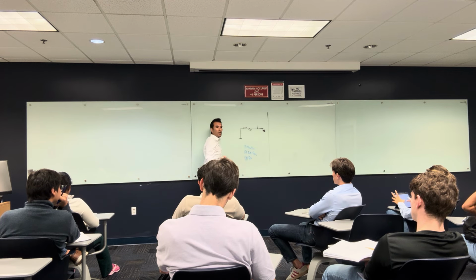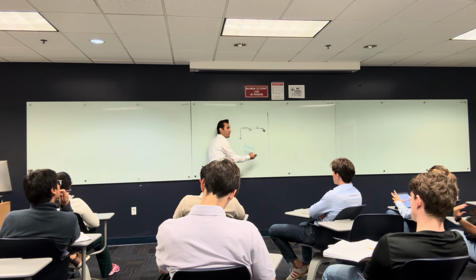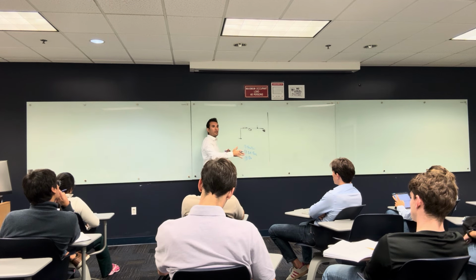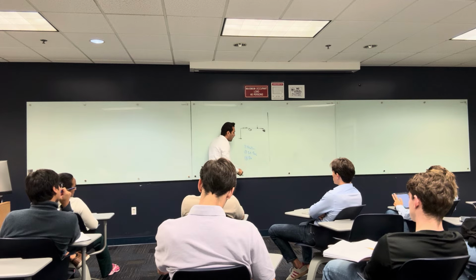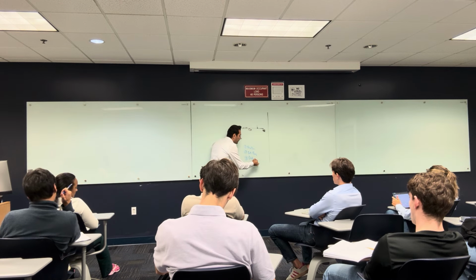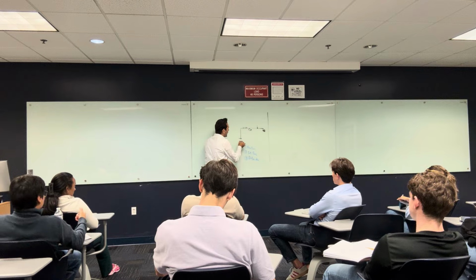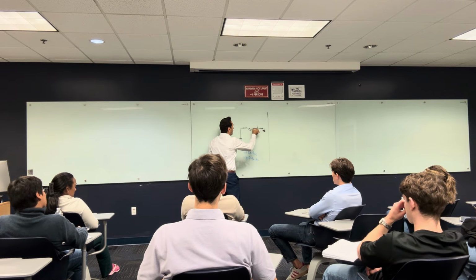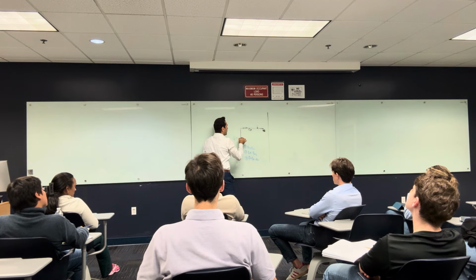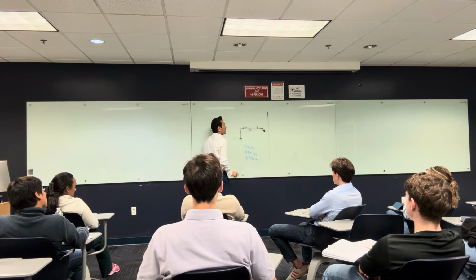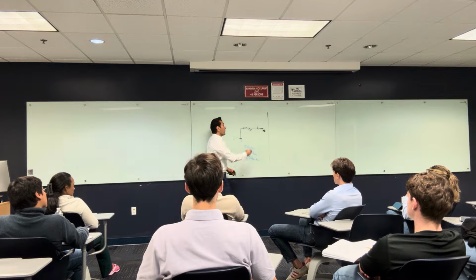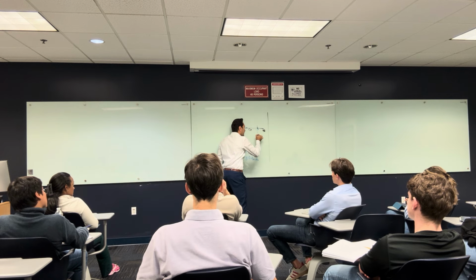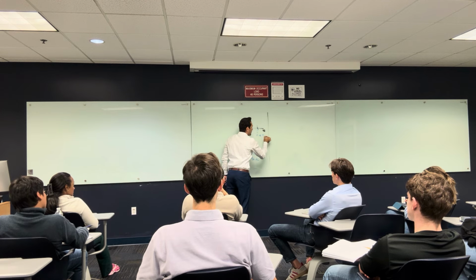But when we design buildings, we use the internal forces, and then in the design process, we convert them to stresses and capacity. So the last thing is deformation, right? I want to know the reaction here and here. I want to know how this structure is gonna perform. It's gonna deform something like this, so I can know if this deformation, this delta, is allowed. Is it less than or equal to the allowed delta? That's why I get deformation.